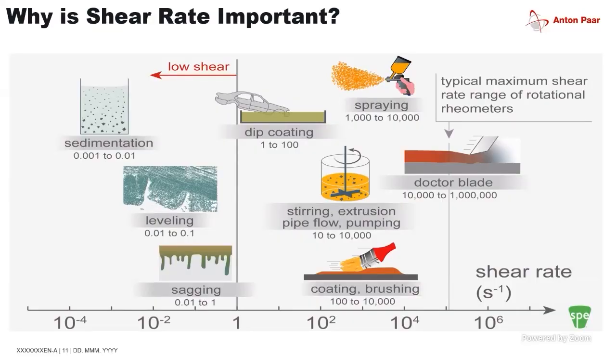And the only reason your viscosity would be the same is if the sample was, in essence, Newtonian. But in the case of most structured materials, as I said before, the viscosity does change. You may have a decreasing viscosity, and so the behaviored response changes. So you have to accommodate for those particular needs and considerations. And so there is a shear rate for every type of application out there.